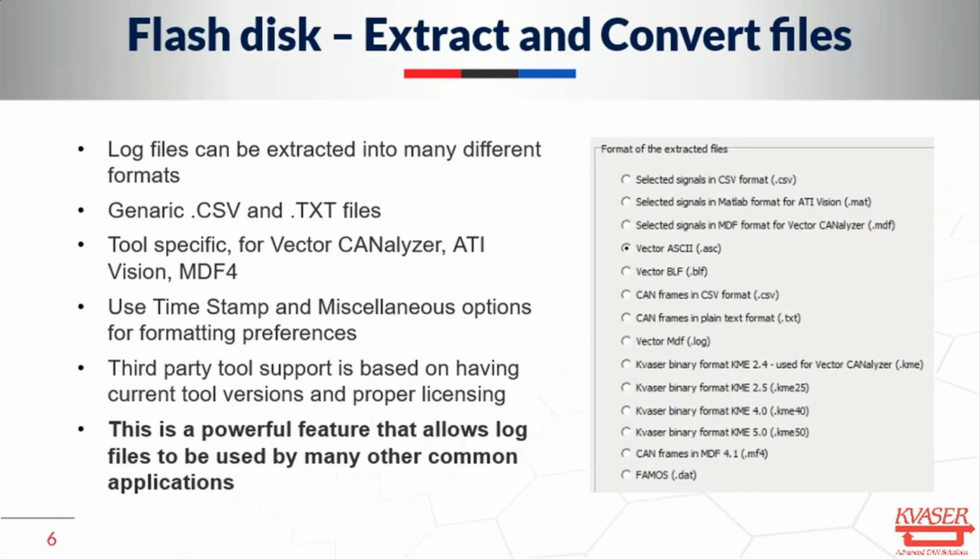So you can format files according to everything on the bus, or you can format according to signals defined in DBC files. So the formatting or extraction option does allow you to use DBC files and extract according to the labels as well. A lot of third-party tools support this extraction scheme. A very powerful feature, it allows log files to be used by many other common applications in the industry.